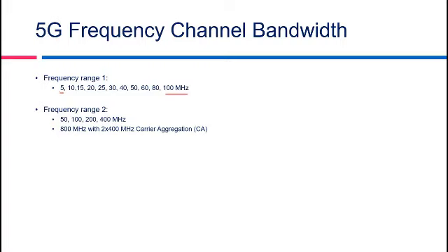One thing to note here is that 5G does not support lower channel bandwidths which are specified in LTE. LTE was able to support 1.4 as well as 3 MHz channel bandwidth, but 5G channel bandwidth starts from a minimum of 5 MHz.